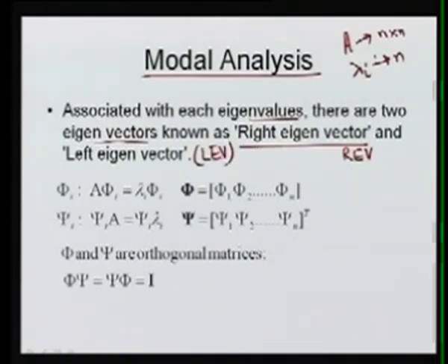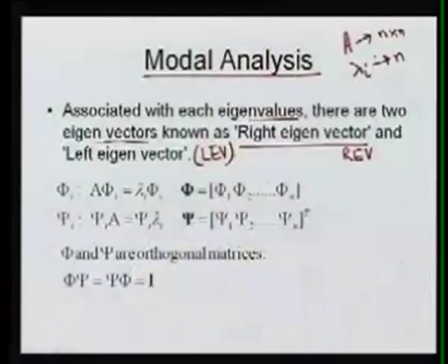These vectors are very good for giving a lot of information, basically the participation analysis they normally provide. So how can we get it? We know this A transition matrix. If you are going for the right eigenvector, using some vector phi that satisfies A phi i equals lambda i phi i, for all i, this phi will be nothing but your right eigenvector, because it is on the right hand side.